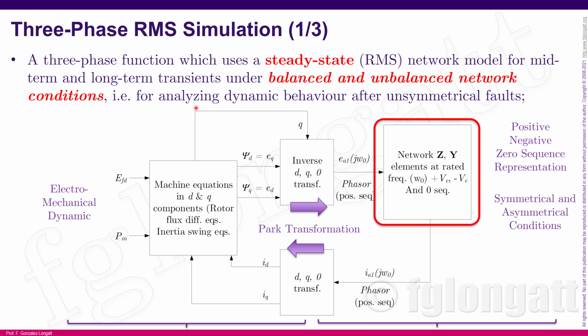If you are interested in asymmetrical conditions, if you are using, for instance, a line-to-line short circuit, you need to select this three-phase RMS simulation. Okay, be careful with that. Please keep it in mind. Okay.